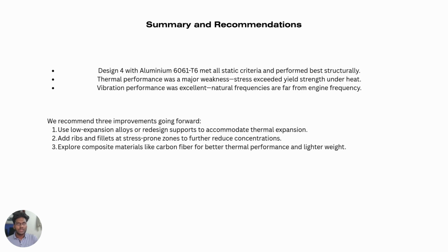So, Design 4 with aluminum 6061 T6 met all static criteria and performed best structurally. Thermal performance was a major weakness. Stress exceeded yield strength under heat. The vibration performance was excellent and natural frequencies are far from engine frequency.